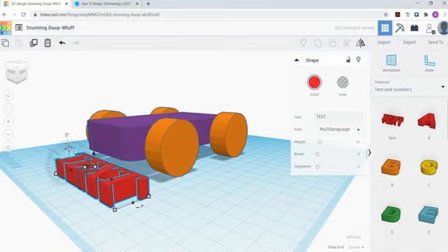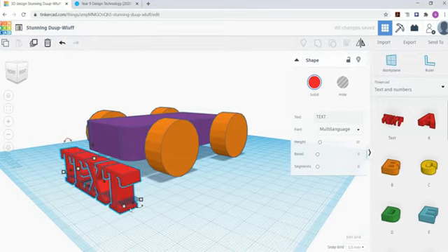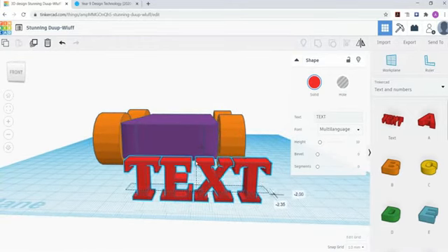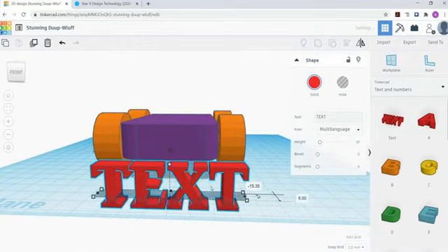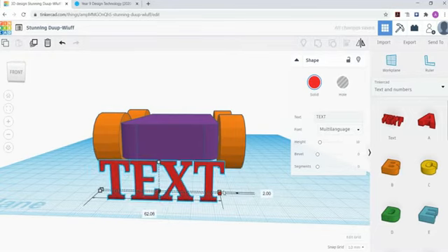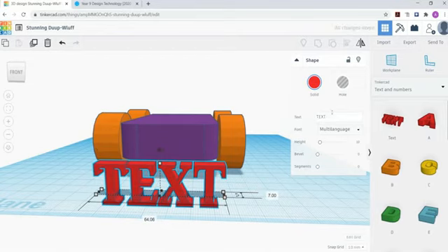You can see the circle circumference, right? The protractor there. Click on it, then press on the 0, and then change it to 90 degrees, and it will stay upright. I'm going to put this text into the box over here. As you can see, the text is quite big, so just make it smaller. And not only that, I'm going to change the text. You just type over here.